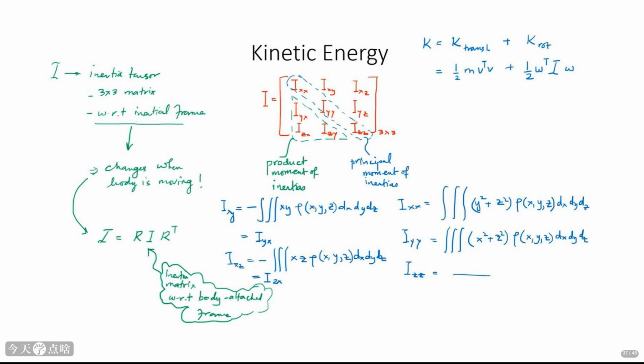When calculating the total kinetic energy of a multi-link robot, we need to consider both the translational motion of each link's center of mass and its rotational motion. The inertia tensor I is crucial for the rotational part. It's calculated based on the geometry and mass distribution of the link. The diagram shows the components of the inertia tensor and how it relates to the moments of inertia Ixx, Iyy, Izz, and products of inertia Ixy, Ixz.